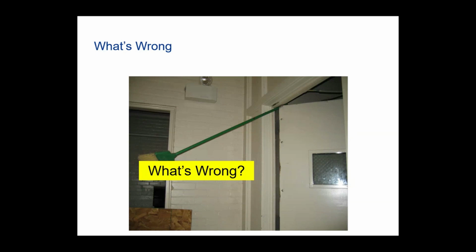This, to me, is a lot cheaper door stop than what you saw before. This one, by throwing that broom in there, you can quickly operate that stairwell to where you can take trash and things like that through there. But the broom is not rated for fire or life safety. So keep that in mind. If you're scheduling brooms at stairwells, you might have a problem with your AHJ.